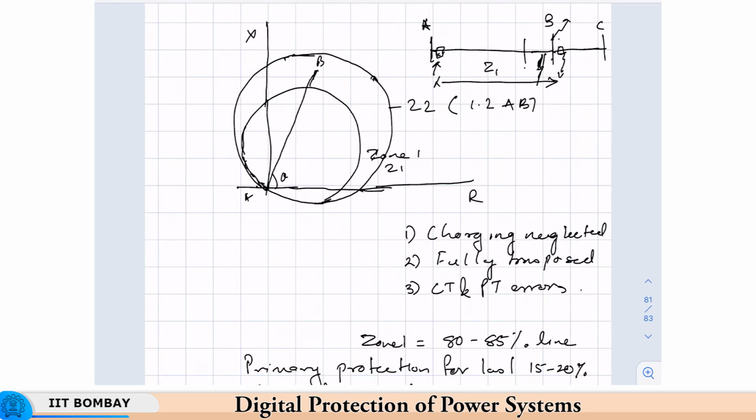What happens with numerical relays is your code is just a part of a single algorithm. So you will have these 6 checks for phase faults, and then earth fault. The six equations that we described earlier, and it is continuously checking.